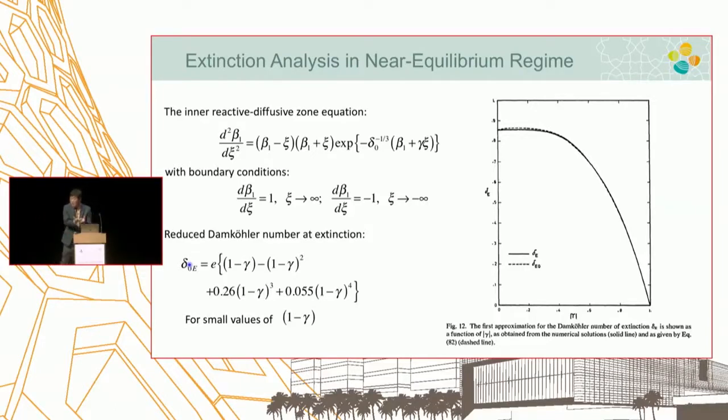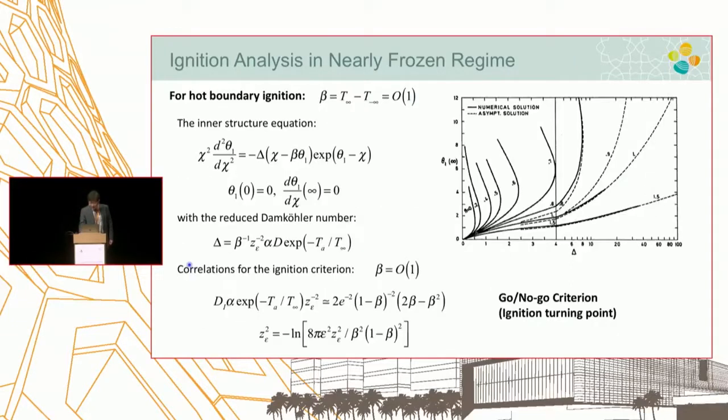Of course, it's a one-step chemistry model. So if you want to extend it into detailed chemistry, well, there's a limitation. But as we have seen many times, if you run opposed-flow calculations, I will show you the mechanics behind it, you do reproduce this perfect turning point behavior using GRI-Mech on opposed-flow flames. So there's clearly one dominant reaction step, maybe not necessarily one step, but some combination of chemical modes that is responsible for driving the system dynamics into nonlinearity. And it's this nonlinear turning point behavior that is the most critical and important aspect of combustion study.